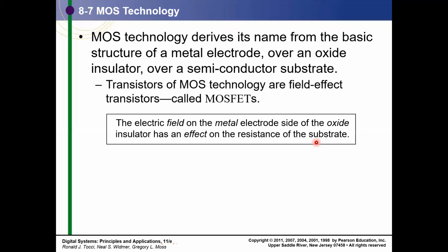Conduction is when current can flow from drain to source or source to drain as per our convention. If I'm talking about an NMOS transistor, the current flows from drain to source, though electrons always flow from source to drain.